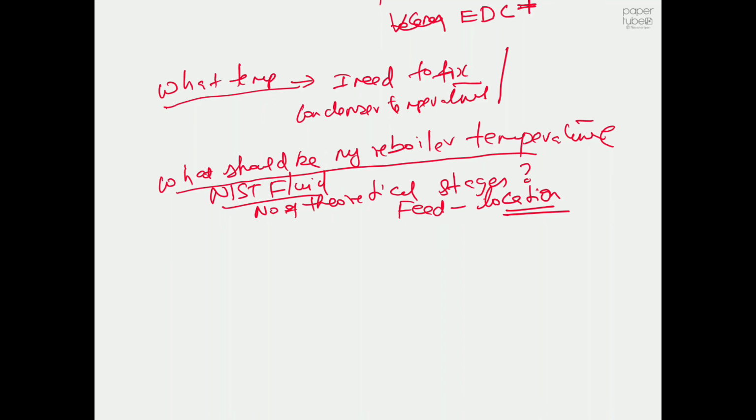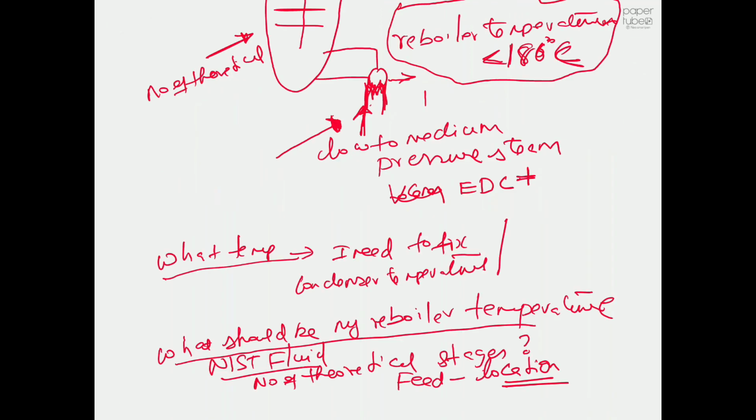We will mix them and purify the final product, and the whole objective is to achieve a purity near 99.5 percent. Then we will pyrolyze that pure ethylene dichloride in order to produce vinyl chloride monomer, and obviously we also need to get nearly 99.5 percent pure vinyl chloride monomer. So we will add a distillation column to achieve that separation.